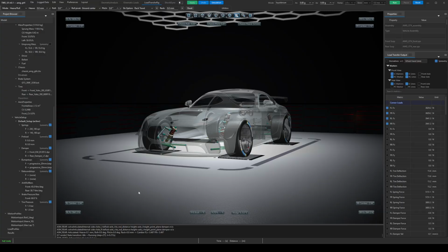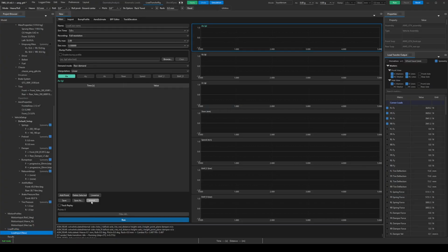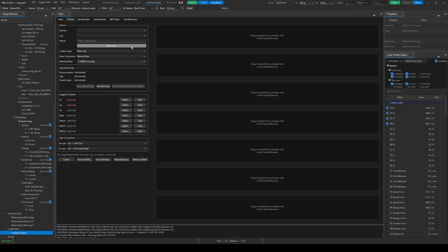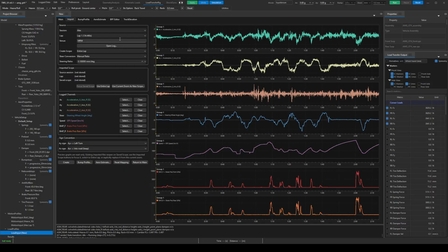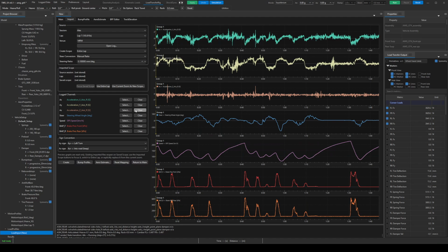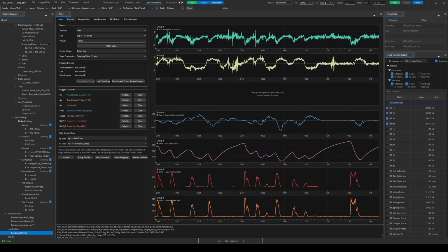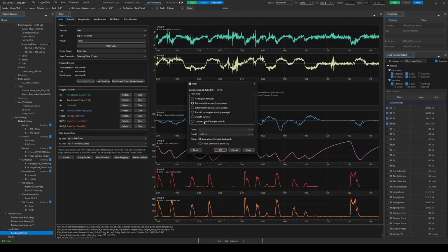Things become more interesting with logged data replay. As in the geometry design module, the user imports a logged track session using one of the supported data formats discussed earlier. The difference is that here, the application replays the real on-track acceleration history through the full multi-body model. The user can simulate the full lap, or zoom into a specific area of interest and run only that section.